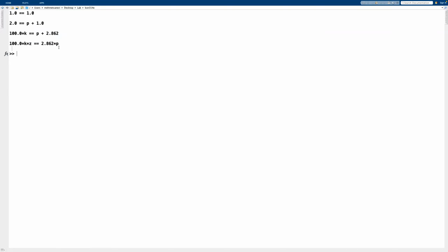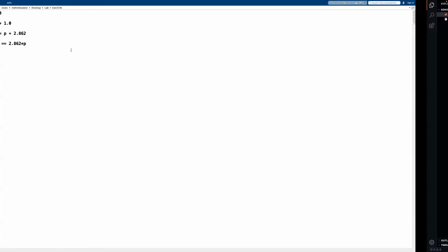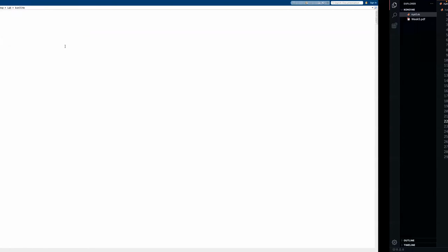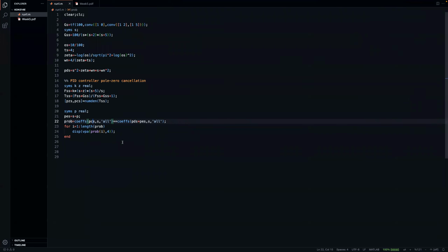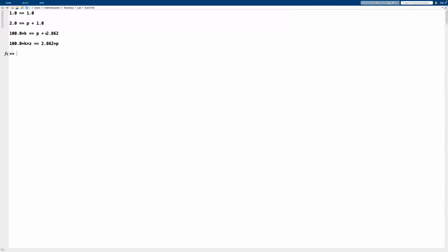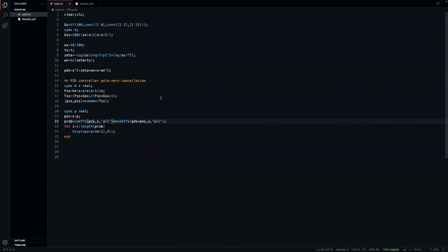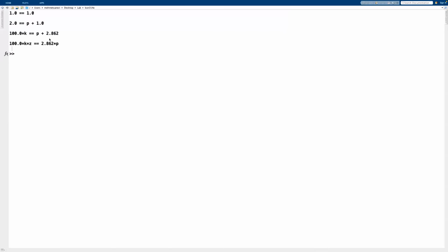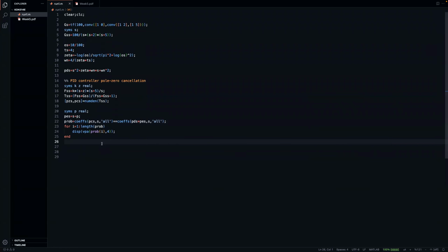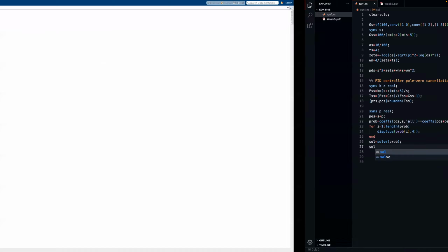It's not linear, not the optimal way of solving this. And this was the reason why I would like to introduce you to KD and KP, or KP and KI, the PD controller design or PI controller design. If you do that, you will get a much easier one. Of course, if the order is not that high, like in this case, it doesn't really matter that much. But the higher the order becomes, the more complicated the problem becomes. So let's actually solve the problem, because we have an equal amount of unknowns and equations. What we can do is just look up what the solution looks like.